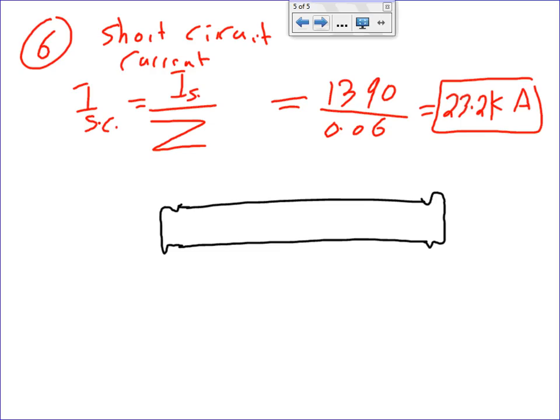Was it 1600 amp? The secondary was 4,000 amp. And it's a 4,000 amp fuse, and the interrupting rating is 23.2 kiloamp. So since it's available 23, most likely it's going to be 25 kiloamp. So you're going to go buy yourself a fuse that's 4,000 amp with an interrupting rating of 25.